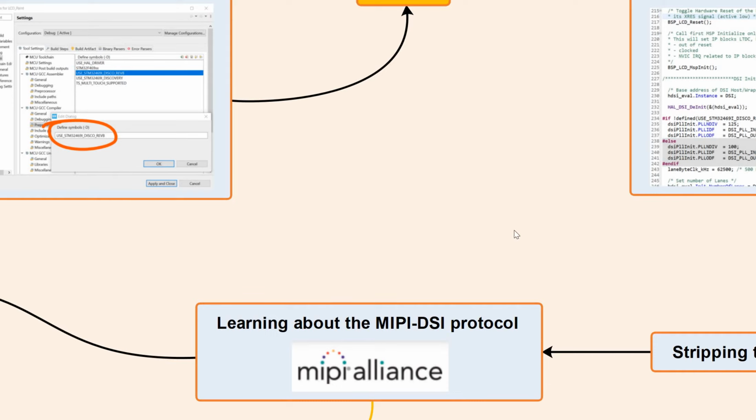And this is a very interesting protocol because it has some advantages, and one of the main ones is the reduced pin count necessary to connect such an LCD to your integrated circuit. The problem you'd be facing if you were using, say, a parallel interface to connect your LCD while at the same time using a small integrated circuit or a small microcontroller, is that you'd be running out of space, and you'd also be running out of pins, and you wouldn't be able to connect any additional peripherals or sensors you want on your embedded application.